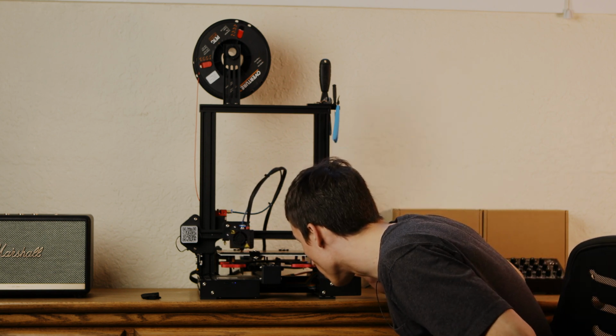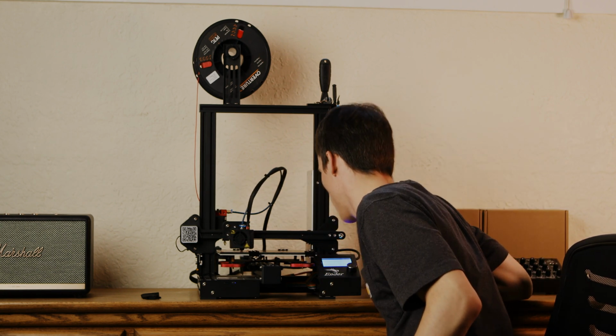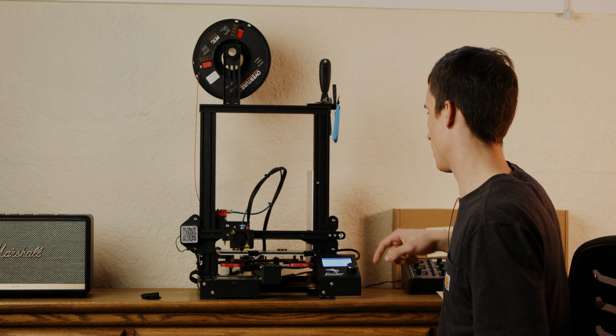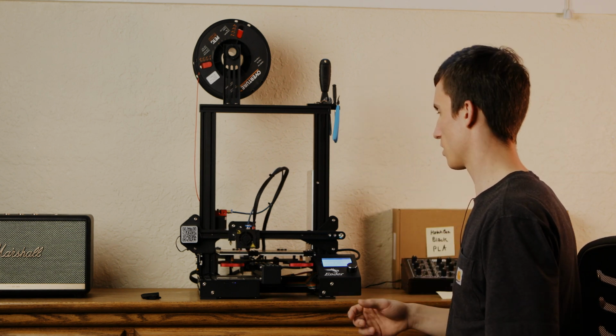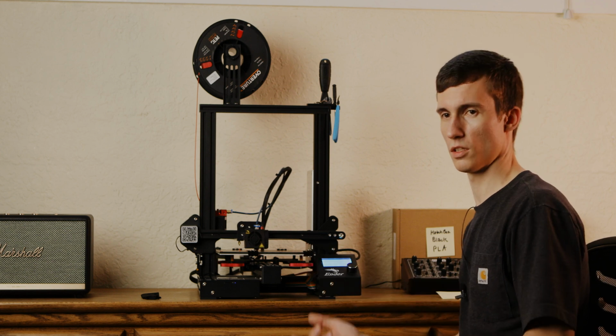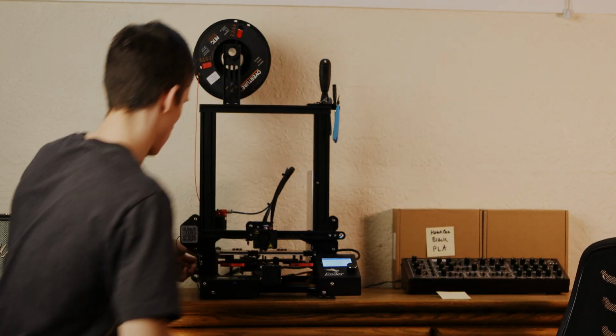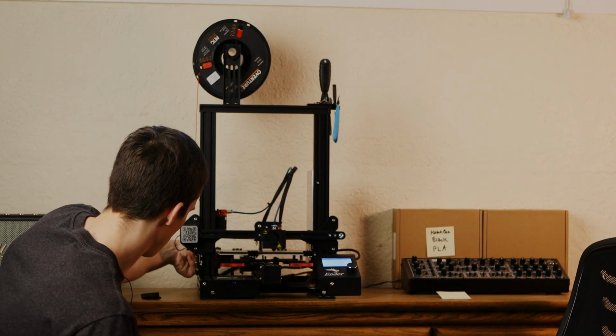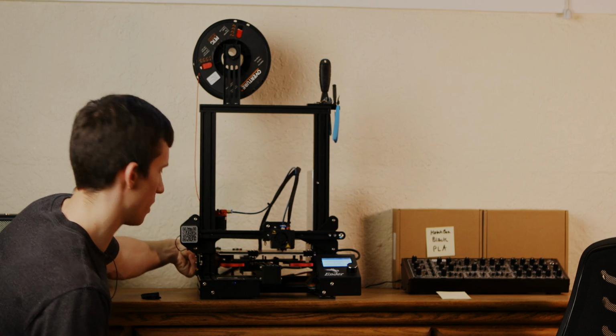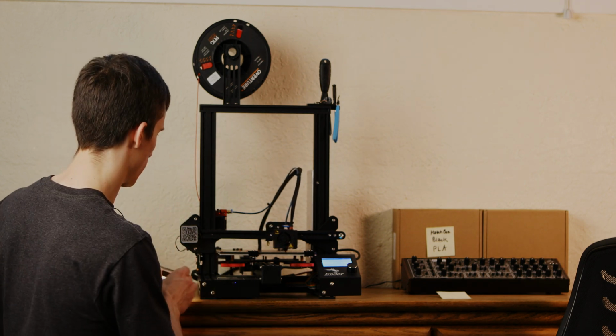that your print didn't turn out well. And yeah, this height for that corner is not working. So I believe it needs to be squished. So I'm going to go ahead and loosen this adjustment screw in that corner on the fly. Just a tiny bit. And then watch that next line as it goes around that corner.